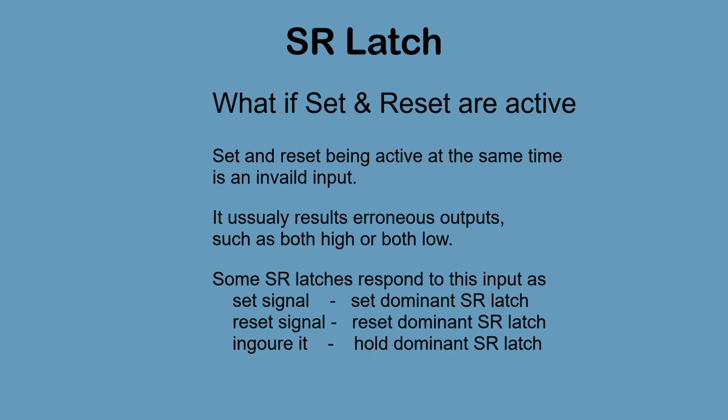They treat it as a set signal, set dominant SRs. They treat it as a reset signal, reset dominant SRs. Or they ignore it completely and maintain their current state, hold dominant SRs.